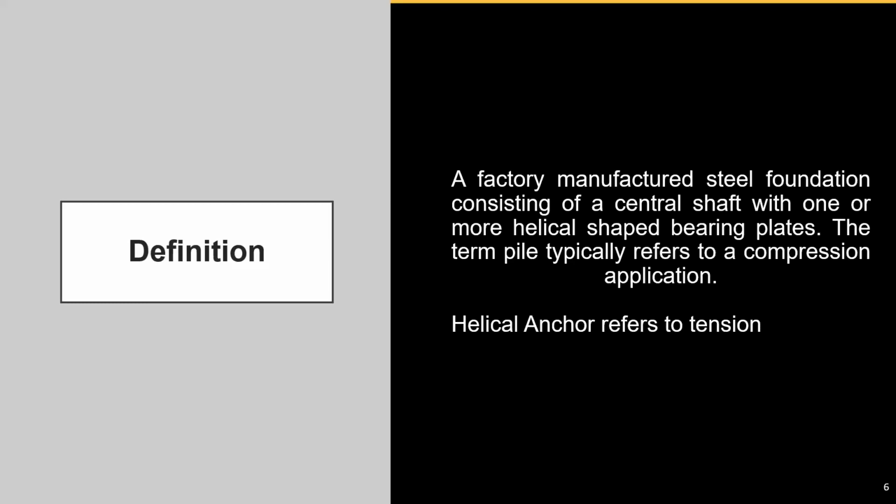And this lecture basically is about small diameter helical piles. Even when you go to the Deep Foundations Institute or some other conferences about helical piles, they're still talking about small diameter helical piles. What does it mean, small diameter helical piles? That means the shaft size has a diameter no more than 4.5 inch. And the reason I choose 4.5 inch is because AC358, if you have a shaft that has a diameter larger than 4.5 inch, they will not evaluate it because it's outside of the scope.